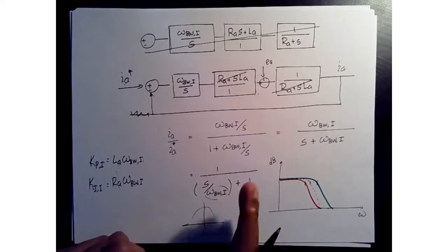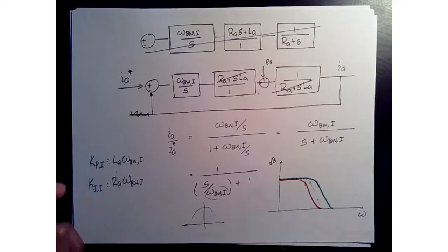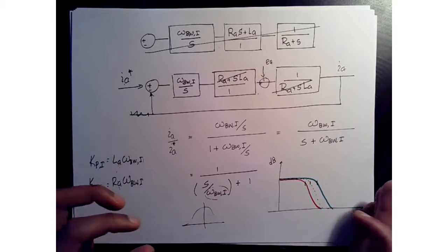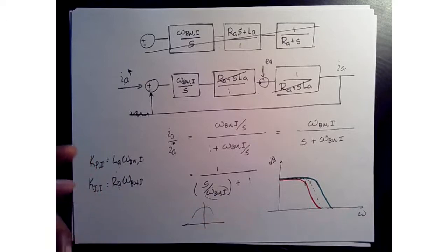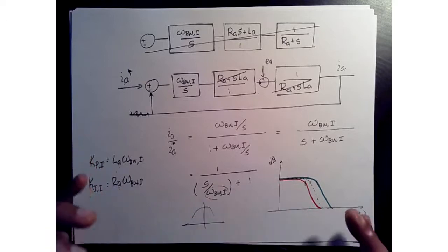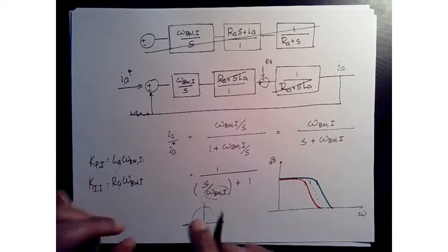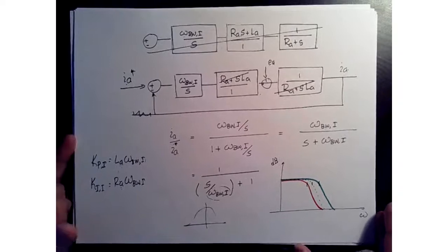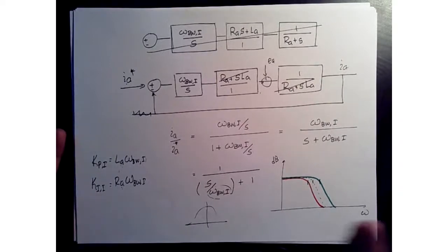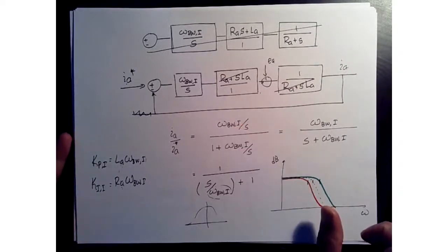They'll say, okay, this is your mean RA value for this batch, and they'll issue one datasheet for that. So there's a certain margin of error in that value. As long as that spread is not too much, the variance is not too large, you can use this method to design a controller. In applications where you know exactly your resistance and inductance, it might work even better.